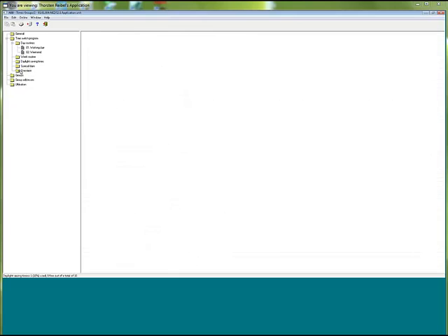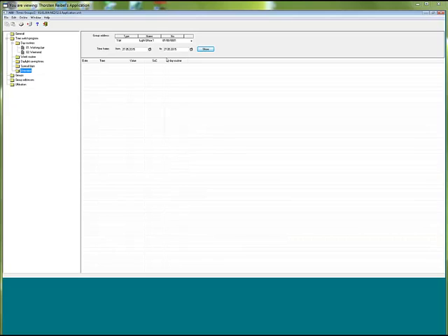Yeah, finally, the overview. So for each group address used for a time function, you can have a look what happens with this function over a period of time. So from today up to next month, you can see right now what happens during the certain days with this function. It's always the same. At 10 o'clock, it will be switched off, for example, but during the working days only. You see, it's not very difficult. If you have understood once this principle, it can be done.